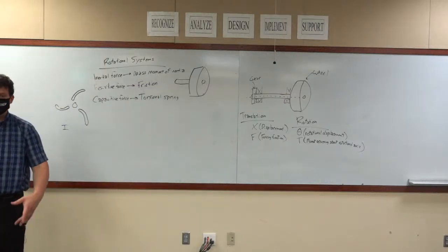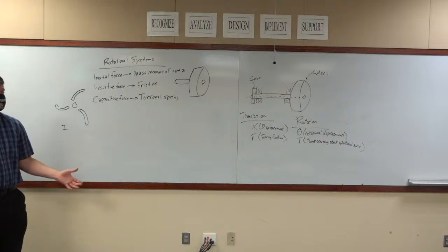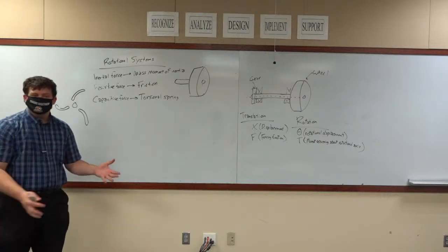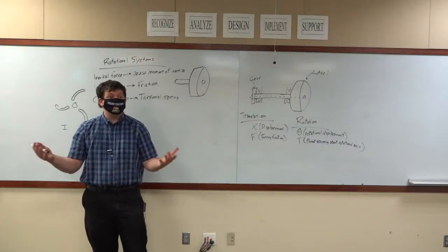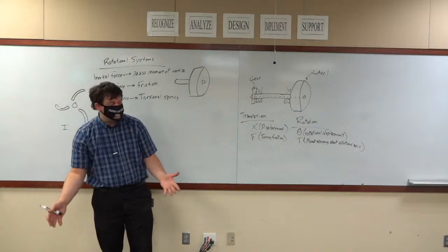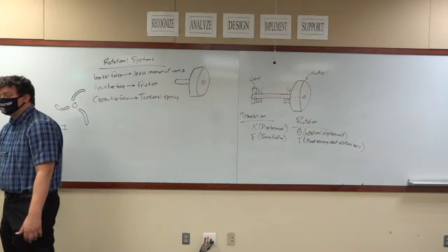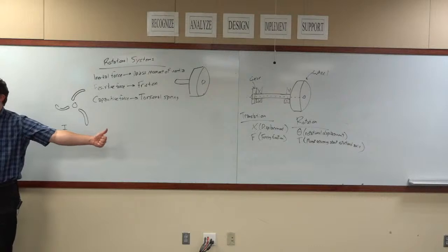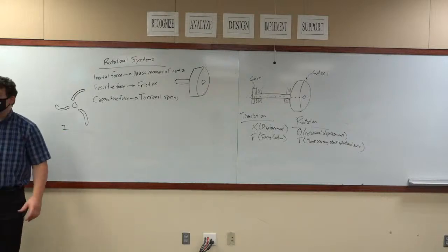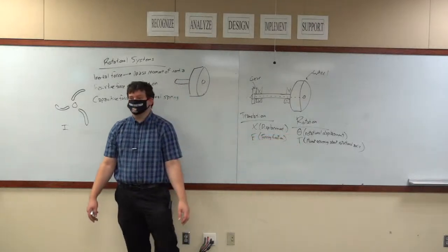So all of these equations are linked by the fact that they all go back to energy. I mentioned this last time. This is very much a study of energy. But this is all the equations, and the energy never even shows up in the math. But we could figure out energy very easily from this just by multiplying these two together. That's it. You can figure out the amount of energy that is being dissipated by the damper. You can figure out the amount of energy that's being stored in the axle by multiplying this torque by the amount of distance that it rotates.